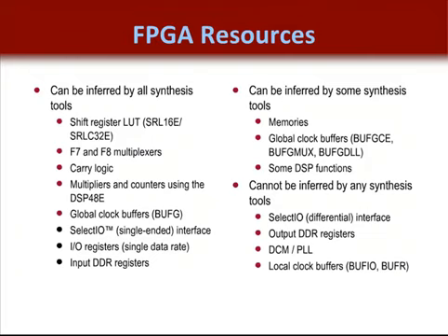There would also be no warning or error message sent by the synthesis tool, since the tool would think you wanted to build a shift register with your standard flip-flops. There would be no error in that. Likewise, the implementation tools would not give a warning or error message, since the netlist made by the synthesis tool would reference flip-flops, and as we know, there's nothing wrong with that.